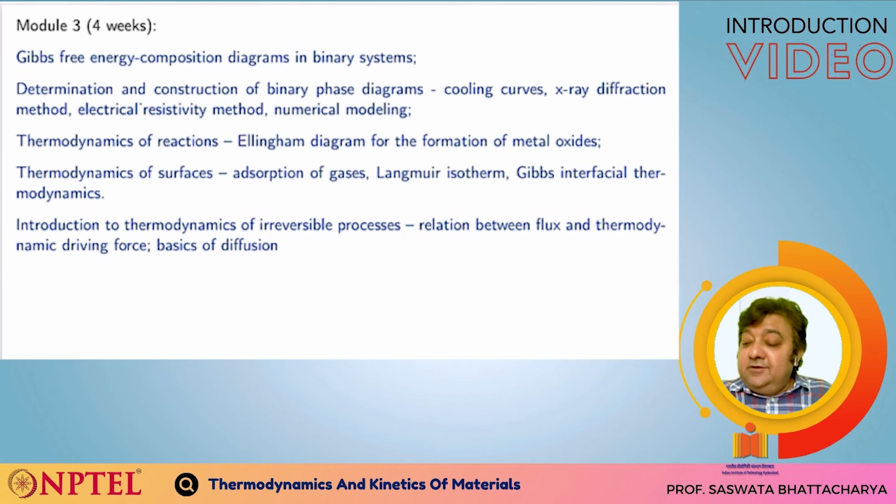So, here we look at how these Gibbs free energy composition diagrams can be used to define thermodynamic driving forces, to understand equilibrium between phases, and how to use these to construct binary phase diagrams. And also, I look at the experimental determination of binary phase diagrams using cooling curves, X-ray diffraction method, or electrical resistivity method.